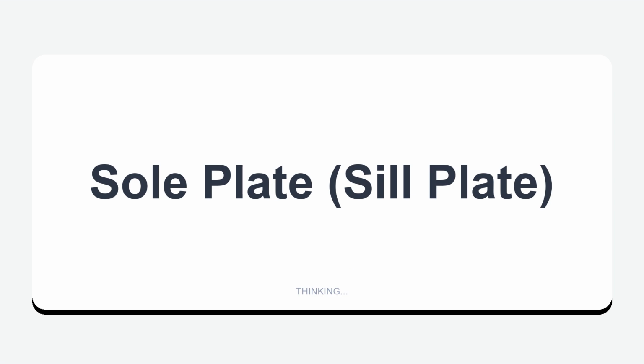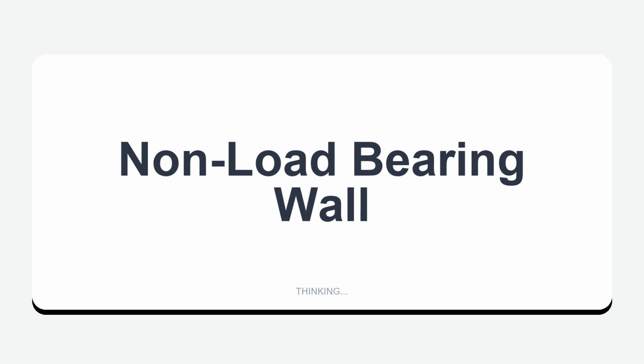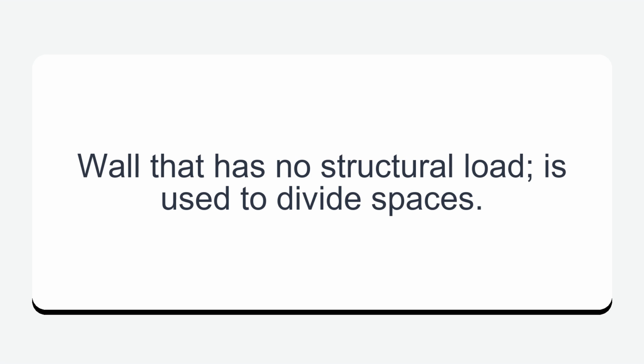Sole plate, sill plate. A horizontal structural member located at the bottom of the studs used to hold the wall together. A sole plate also provides a surface for attaching the wall to its supporting structure. Non-load bearing wall. Wall that has no structural load, used to divide spaces.